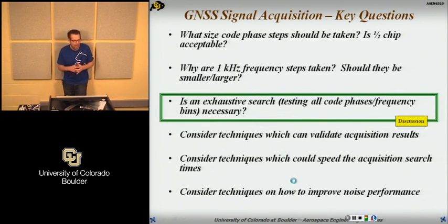So let's assume we have a cold start. We don't know anything. Then we are going to have to try everything. Try all the code phases. We have no idea where the signal is at. On that kind of accuracy, frequency, we've got no idea.